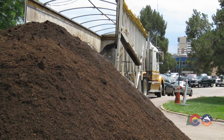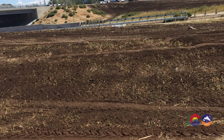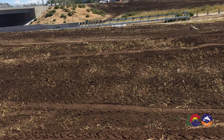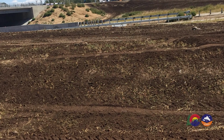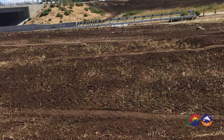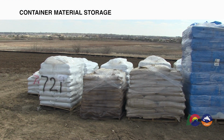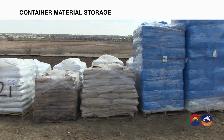In addition, a visual inspection of the compost should be made. Material should be uniform, with no pieces of material over 2 inches. Compost should smell like moist earth. There should be no animal manure odor. Amendments should be stored out of direct sunlight, heat, stormwater, and moisture.